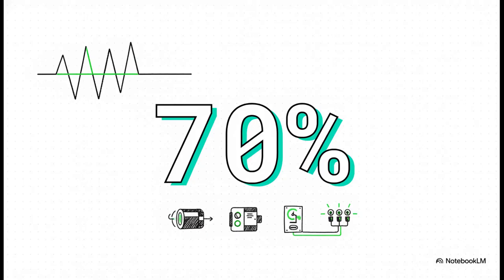And here is your highest hurdle, writing a program to generate exactly a 70% PWM signal. Unlike your previous square wave, which was a clean 50-50 split, this signal is asymmetrical. A 70% duty cycle means the signal has to stay at logic high for 70% of the time and logic low for the remaining 30%. This is incredibly practical stuff. In the real world, this exact timing technique is how we control the speed of DC motors, set the position of servo motors, or smoothly dim an LED array. Getting this right in your software is quite literally what makes complex hardware function smoothly.